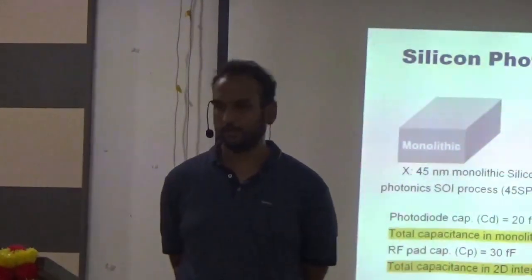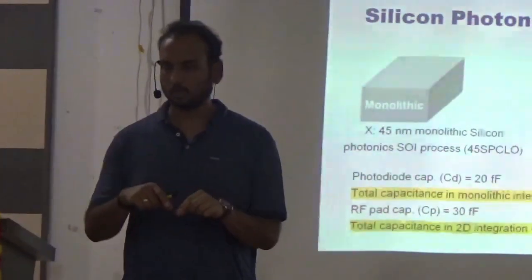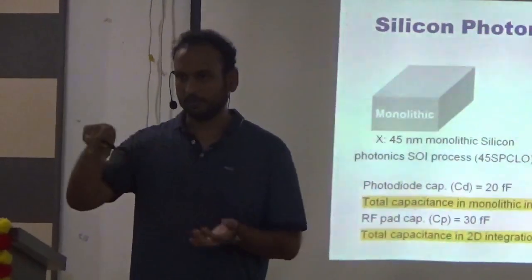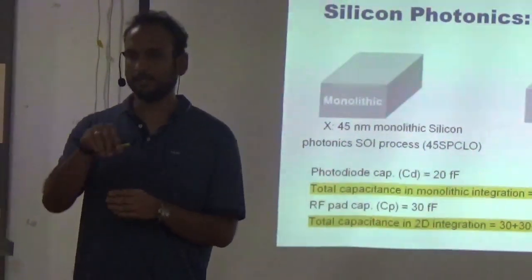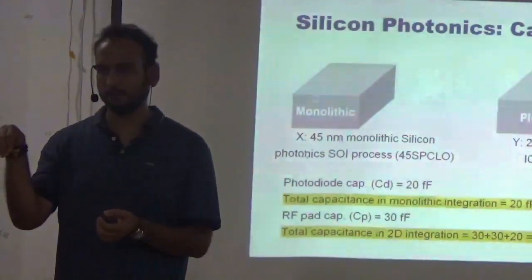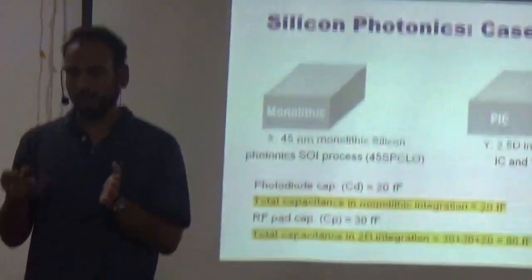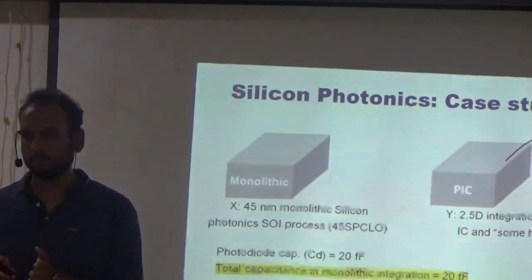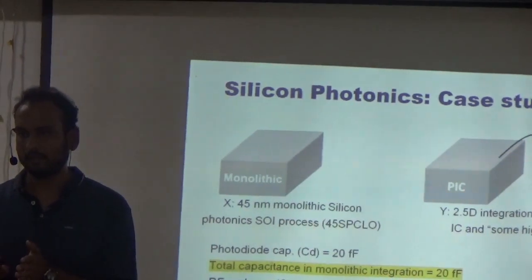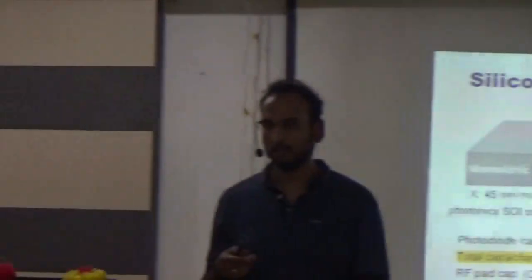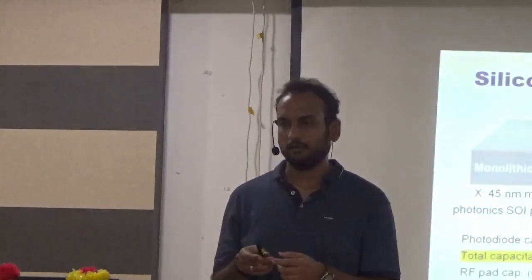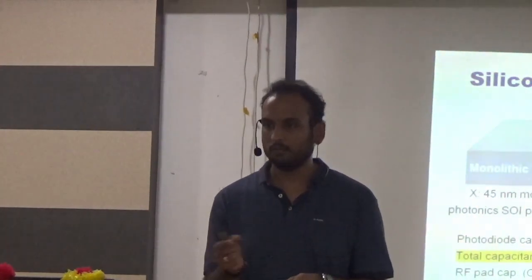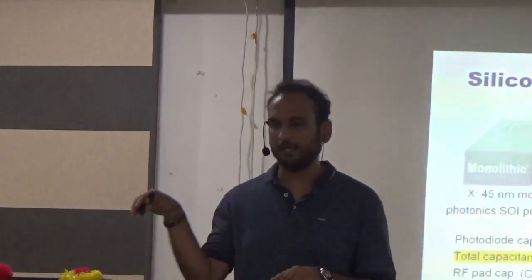Yes, you are right. When we talk about the gap or the transmission line or some kind of interconnect, let's take an interconnect from one chip to another, or one circuit to another. When we make a very narrow transmission line or narrow interconnect, we have lesser capacitance. When we do everything on the same IC, we can create a very narrow metal wire from one end to another.